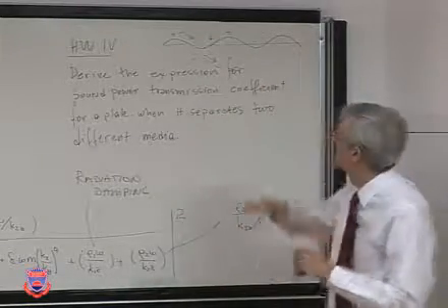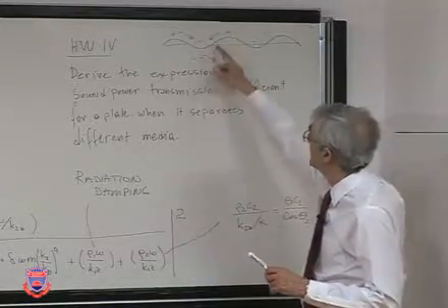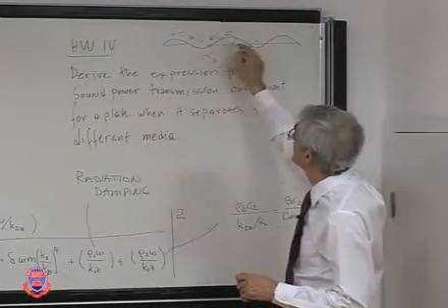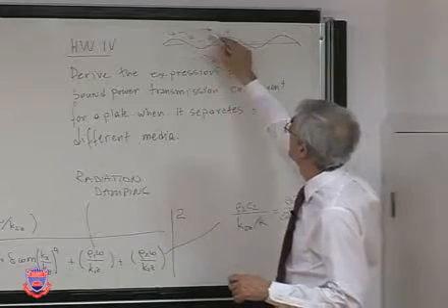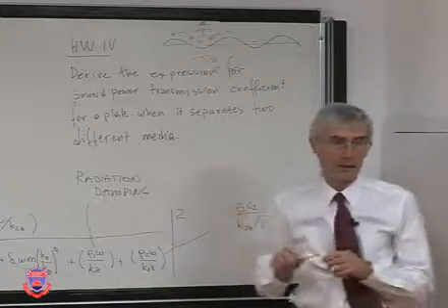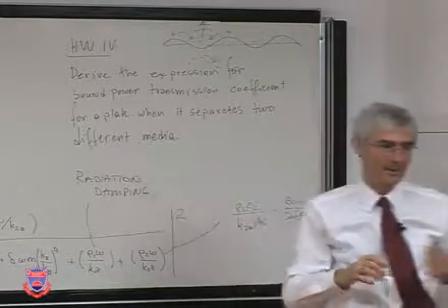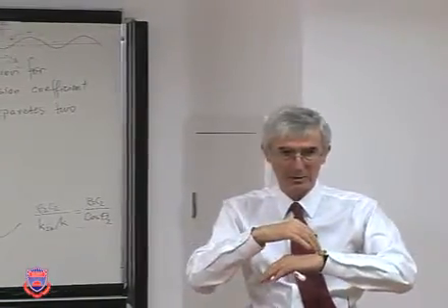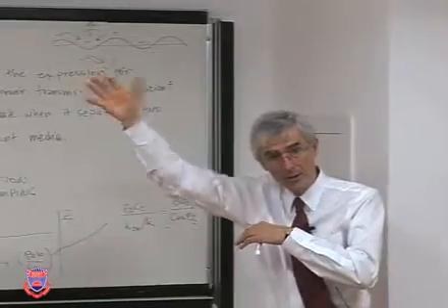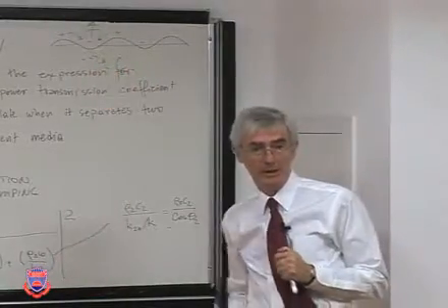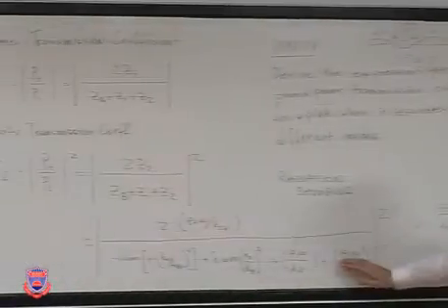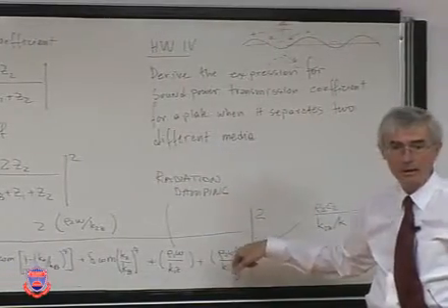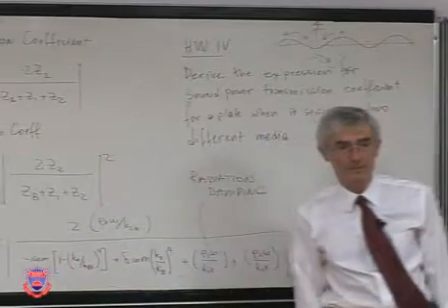But if this were above that coincidence frequency, then it doesn't have time to go back and forth. It would just radiate outside. Physically, that's what happens. In one case, it's reactive, it just stays around the structure. In the other case, the energy just radiates away. So as long as they're real, they're damping. If they are not real, then they are part of the reactive field.